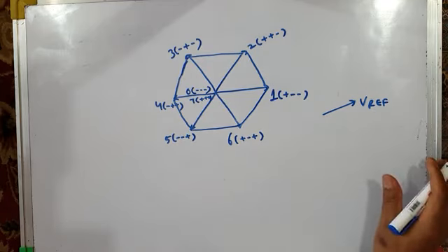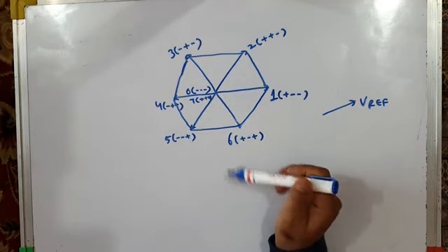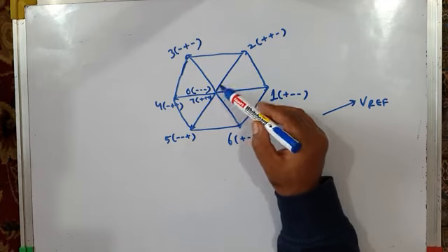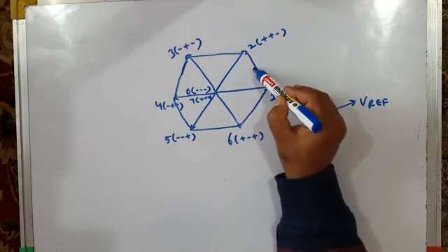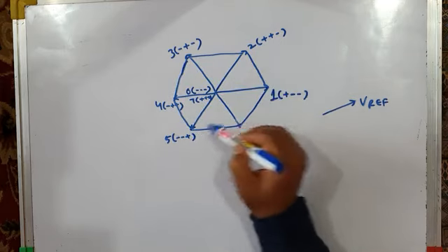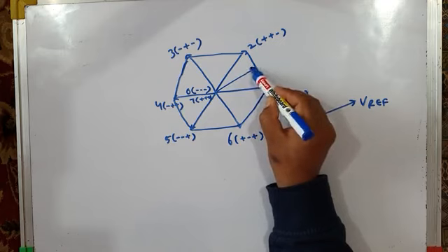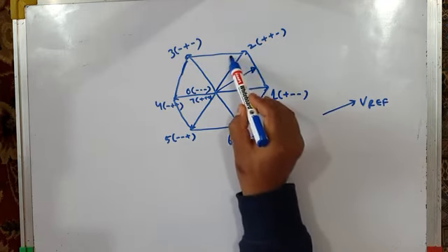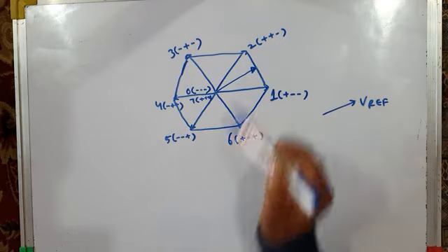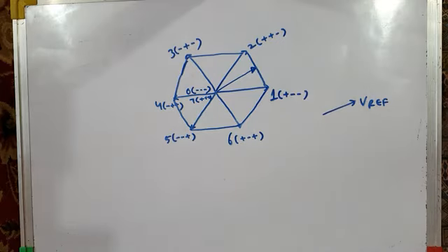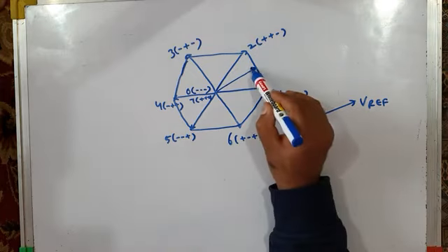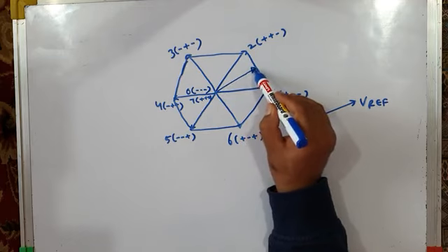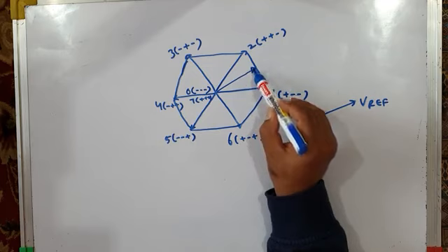I told you that for sinusoidal output voltages, without going into overmodulation, the maximum length of the reference vector should be within this hexagon. I mean, this can be the maximum length of the reference vector, Vref. It cannot go beyond this. And if it goes beyond the hexagon, then that is overmodulation. In one of the future lectures, we'll try to study overmodulation also using the space vector approach. And here modulation index will be almost unity, because this is the maximum length of the rotating reference vector.